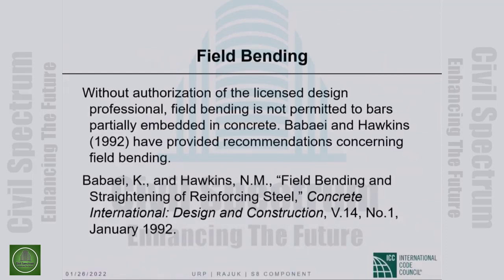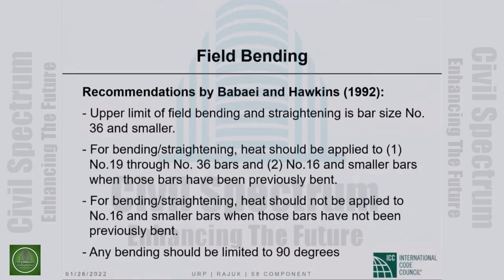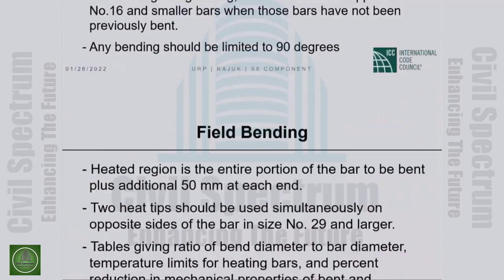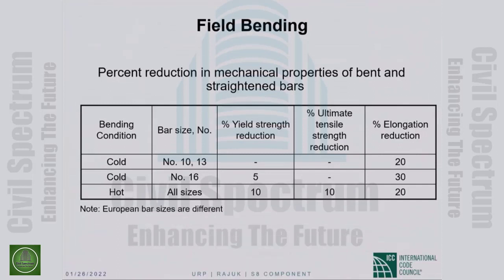Without authorization of the licensed design professional, field bending is not permitted to bars partially embedded in concrete. Neil Hawkins and one of his students have come up with a paper that is excellent on this subject. They have recommendations concerning field bending in that paper that you can look up, and I have 3 or 4 slides summarizing their recommendations, which I definitely will not go into in this short presentation. But this is very good stuff.